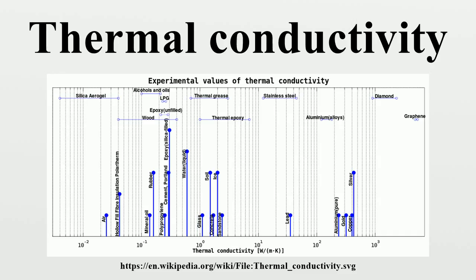Resistance. Thermal resistance is the ability of a material to resist the flow of heat. Thermal resistance is the reciprocal of thermal conductance, i.e., lowering its value will raise the heat conduction and vice versa. When thermal resistances occur in series, they are additive. Thus, when heat flows consecutively through two components each with a resistance of 3 °C/W, the total resistance is 3 plus 3 equals 6 °C/W.